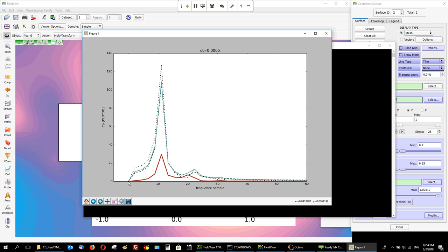The first spike here corresponds to the vortex shedding, really. Again, it's a very simple flow, so there's one frequency for the vortex shedding, and that will also give us the Strouhal number that characterizes this flow. On a more complex flow, you will get more spikes, obviously. You will see frequencies, for instance, present in different areas of the region, like the turbulent boundary layers will typically be very frequency rich.